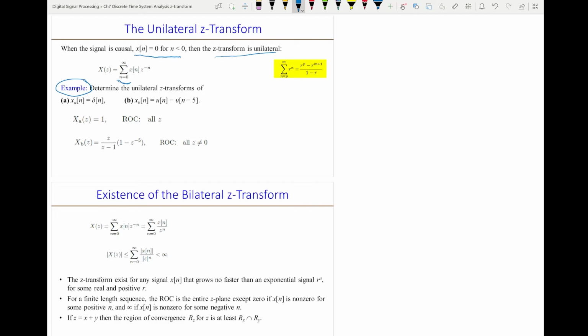Okay, so this example, part A, find the Z transform of this impulse. If I plot x of n, it's just an impulse at n equals 0. So even though it's a simple signal in the time domain, because at negative n it's 0, then suddenly jumps to an impulse, then goes back to 0, this sudden change means it has a lot of frequency content. So we expect the spectrum of this impulse in the Z transform to have many, many values.